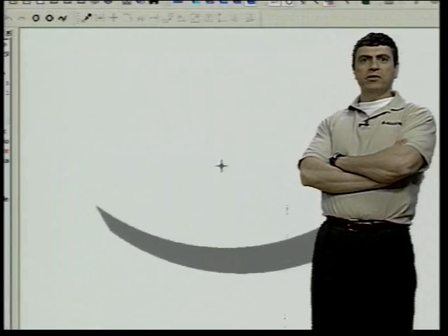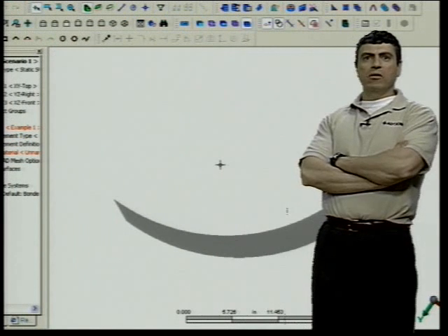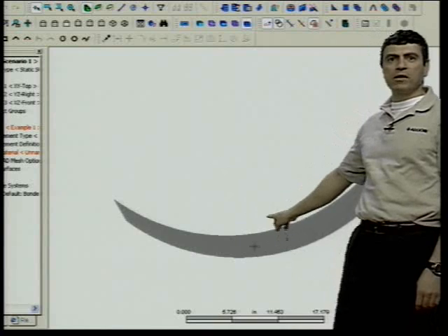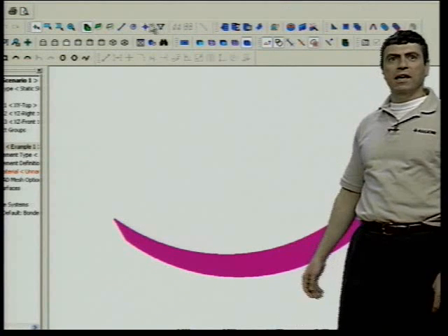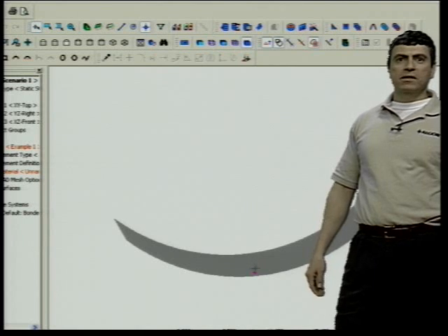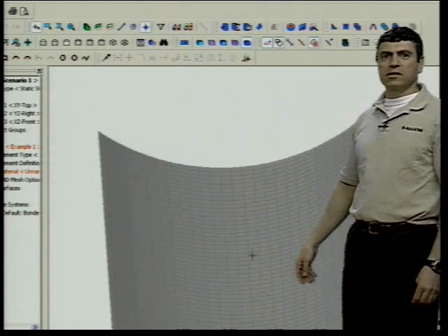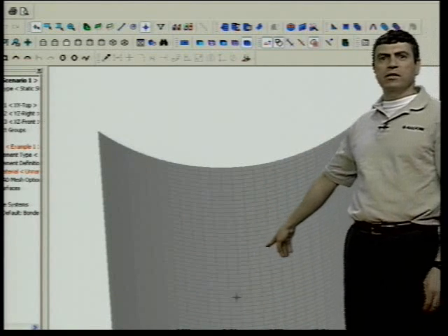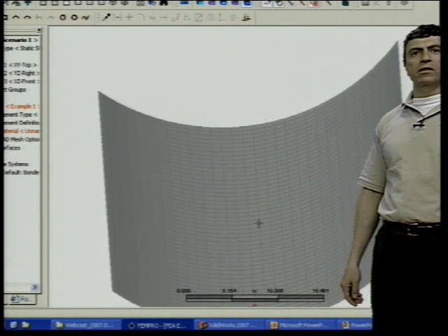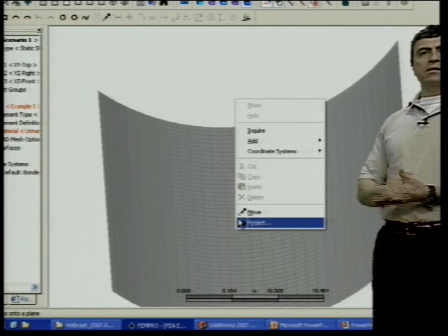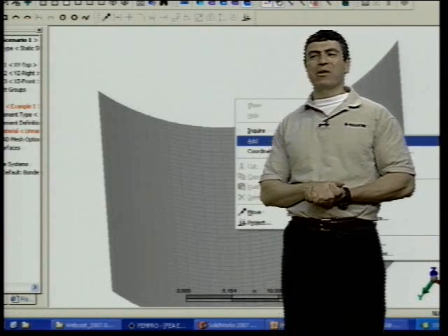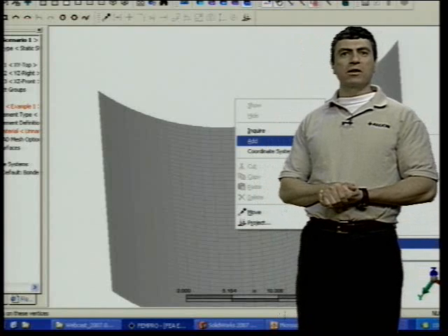And actually, to demonstrate the point here, I'm going to have Joe select a point in the middle of the whole part. If you rotate it a little bit so we can see the lengthwise, this is the z-axis, I believe. Select the point somewhere in the middle and set that as a refinement point, because this turns out to be a very structured mesh, even though it came in from a CAD model. Just due to its geometry, it comes out pretty structured.